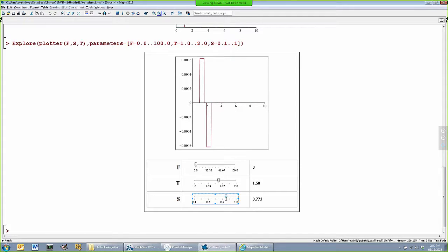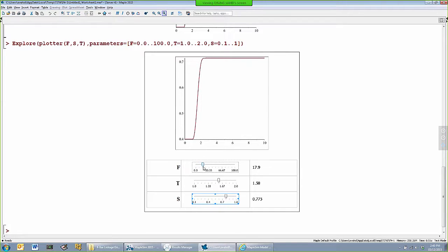I can add more options to this to calculate the total power or total energy required by the motor as well. However, in this particular model where the inertias are small and the acceleration is not too great, the dominating force could quickly be the external force. As I increase the external force, basically it will dwarf the requirement from just looking at the inertial forces.